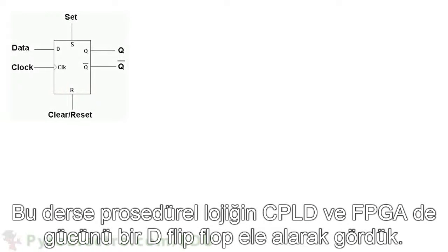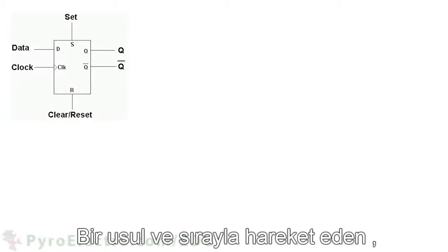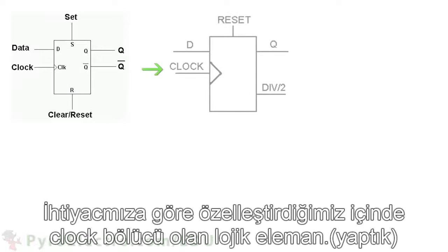In this lesson, we explored the procedural logic power of CPLD and FPGA to take an element like a D flip-flop, which behaves in a procedural and sequential manner, and customized it for our own specific needs into a logic element with a clock divider inside of it.